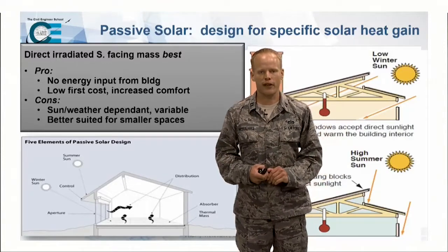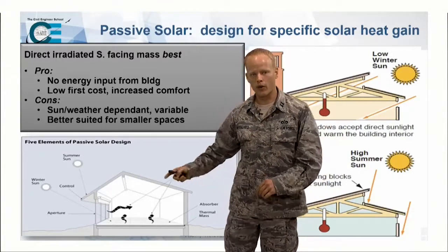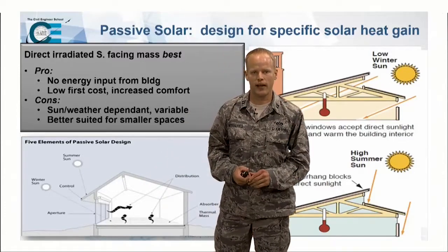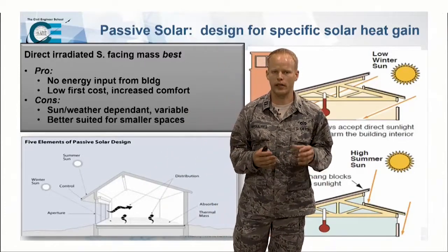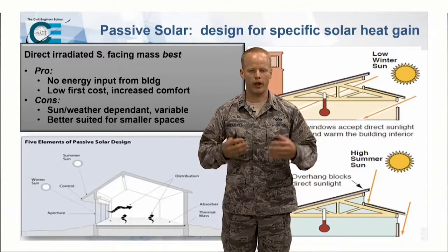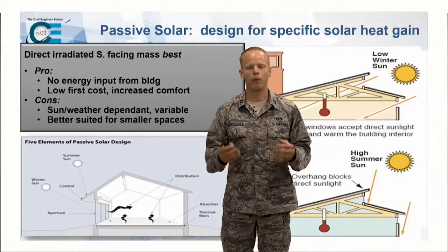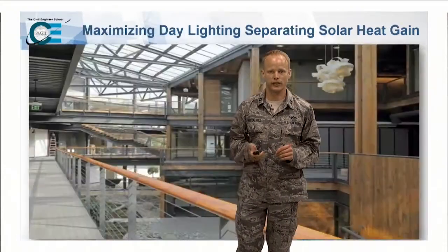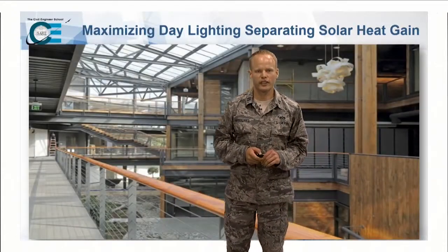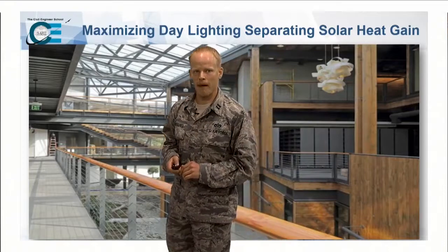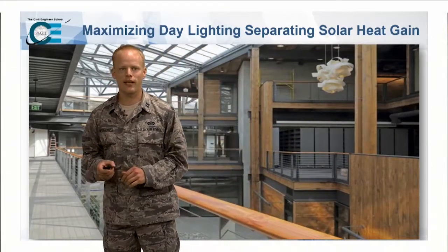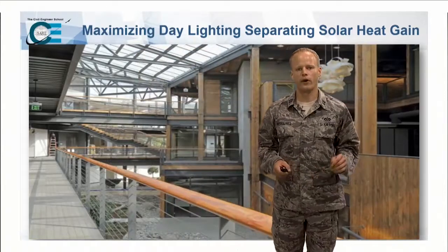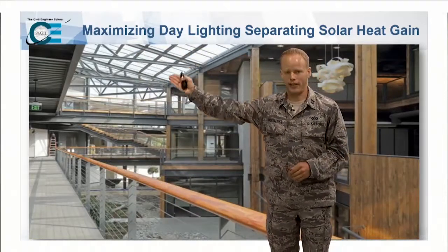Another option we can have on here, and it's shown down over here, is you heat up a wall inside your space. And by heating up the wall inside your space, you then bring energy into the building without bringing light into the building, possibly going against your daylighting strategies. So here's an example of maximizing your daylighting strategies. You can see about where my head is. I'll move it.